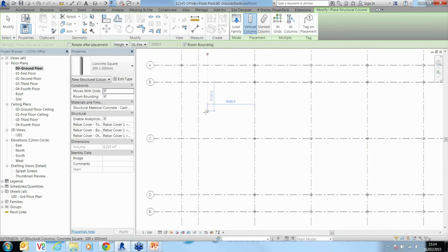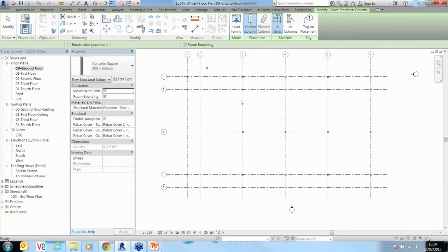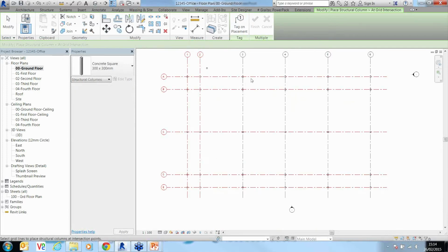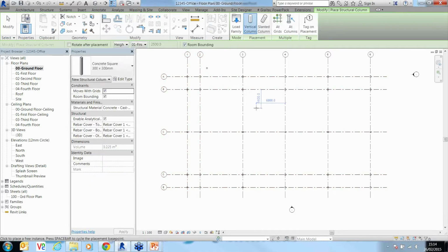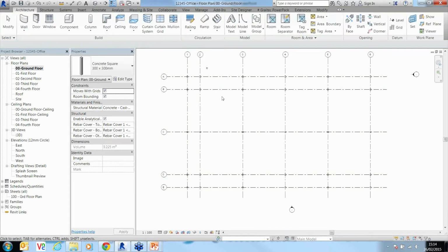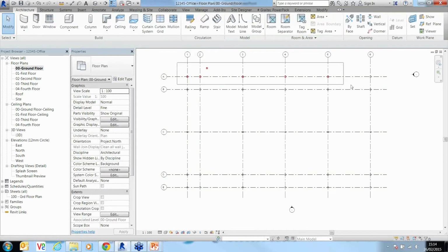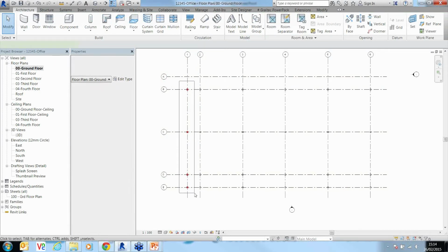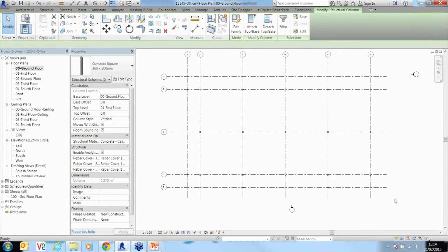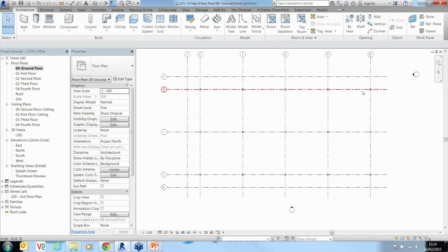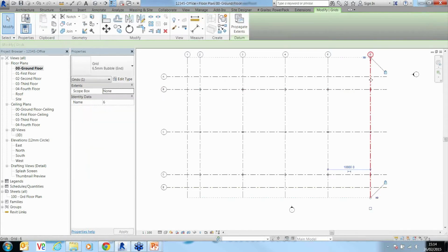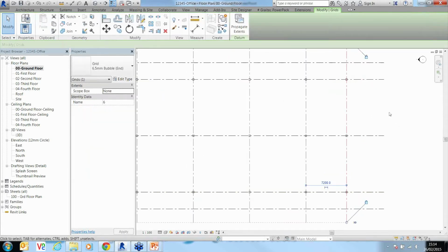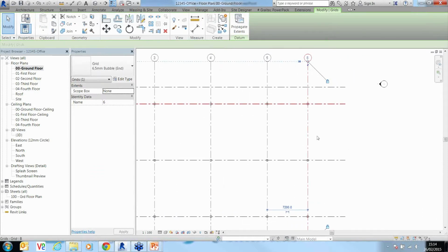So you'll see here there's none been placed. So again, I can select the same again, window over here, I'm just going to select the grid, I'm just going to place them. Okay, simple like that. Now, if I don't want any, I can simply window over and remove them from certain locations. So if I was to, for example, just delete a few off here, you'll see it removes them for me. Okay, I can move the grid line, and you'll notice that the actual elements which are on the grid will move with it. Okay, so again, if I change the dimension, it's going to move them with it.